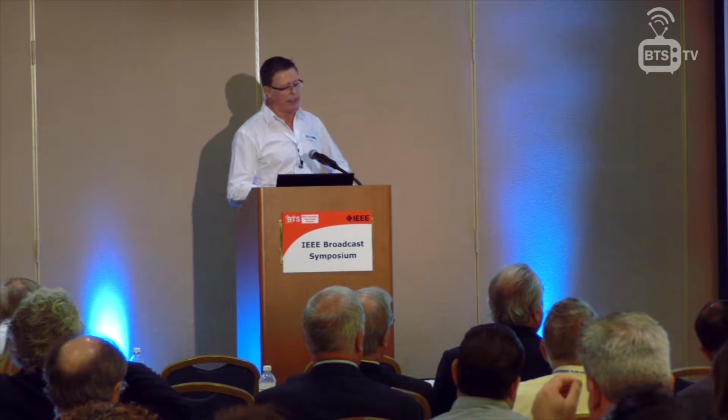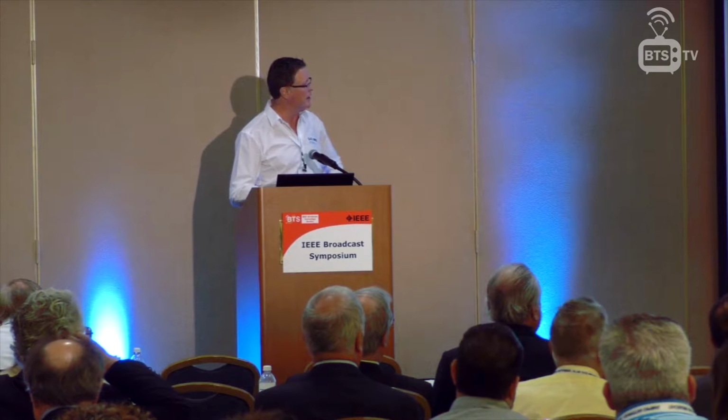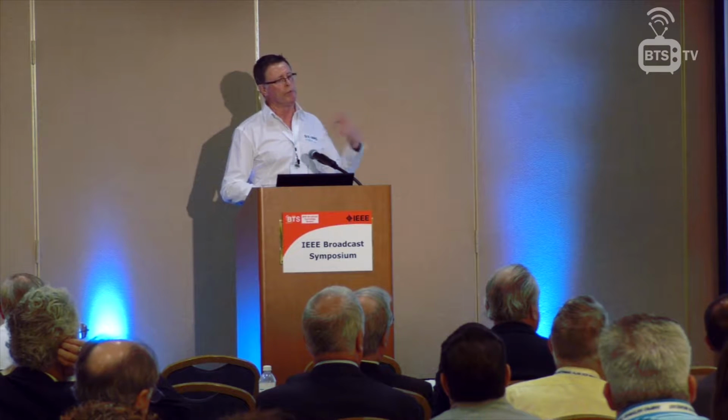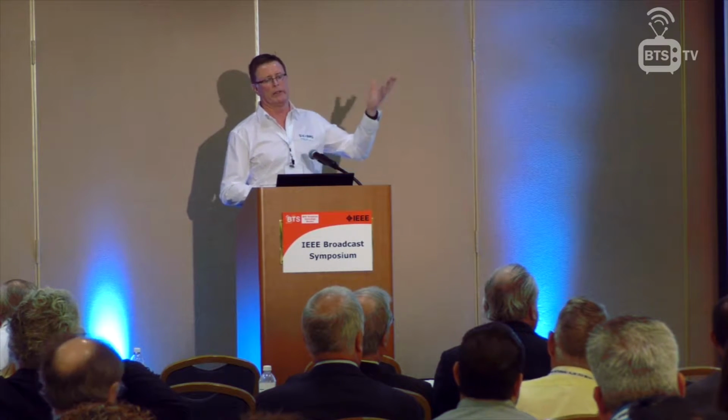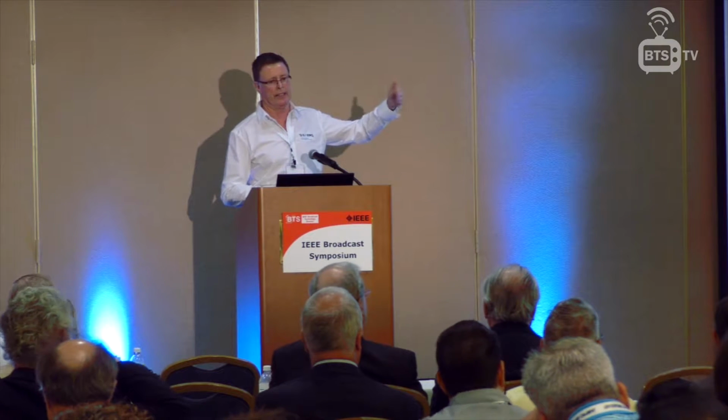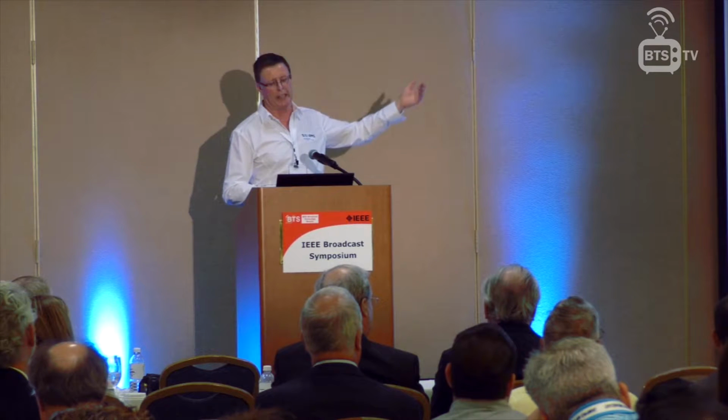So the hardware, what does it consist of? It is a vehicle with an antenna. We've got an integrated spectrum analyzer and PC sitting underneath there. You can hardly pick it up. It has a high resolution GPS and a telemetry link down to the ground control station. In terms of the software, we pre-program the drone with the flight path, and the drone actually flies on autopilot once it's up in the air, and it flies the path. If we're doing an HRP, it's a circle with the drone's antenna pointed towards the tower, the antenna under test.